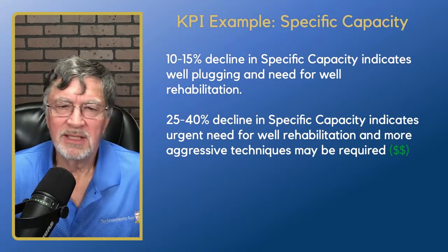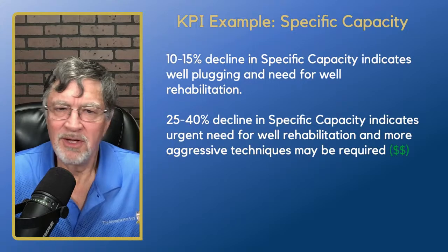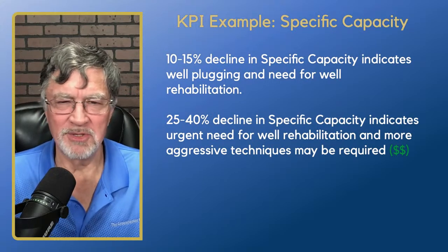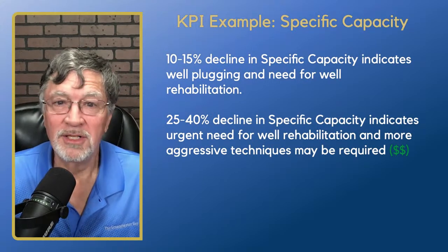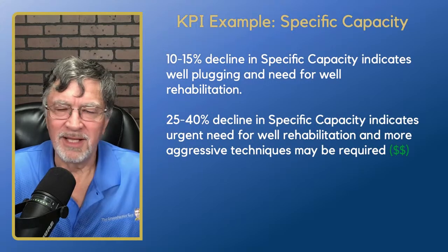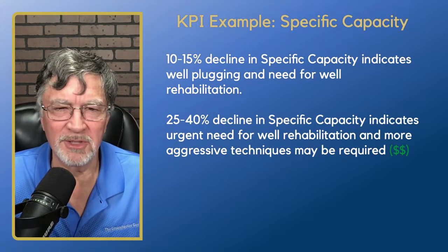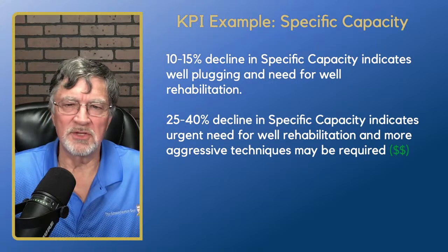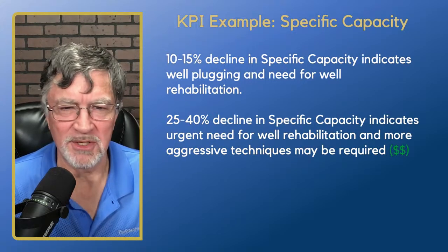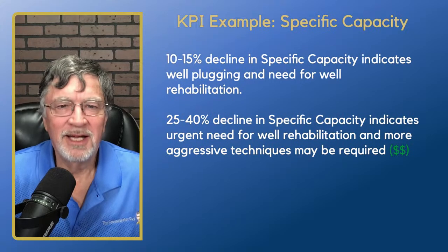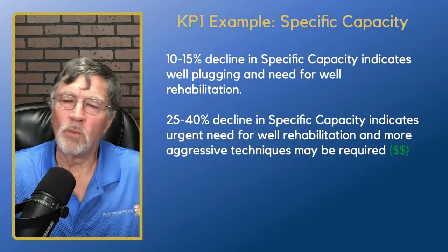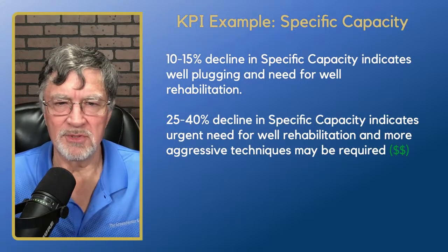of plateau out. And what'll happen is that the water's getting through somehow, and I've got some well videos that just show some amazing circumstances. You wonder how any water is getting into that well, and so at some point, the last little crevice, that last little hole, last little pathway through the mineral incrustations or the biofilm, all of a sudden seals off, and boom, you go from 40% decline in specific capacity to 100% decline in specific capacity, and there's no water coming out of your well. So this is the urgency and why tracking this particular KPI is important.